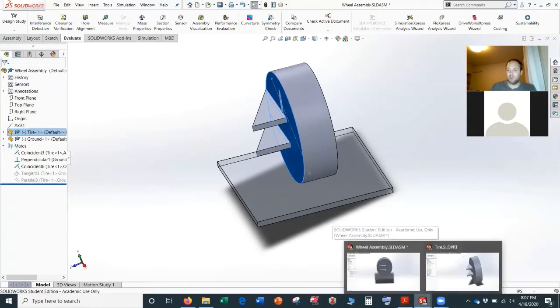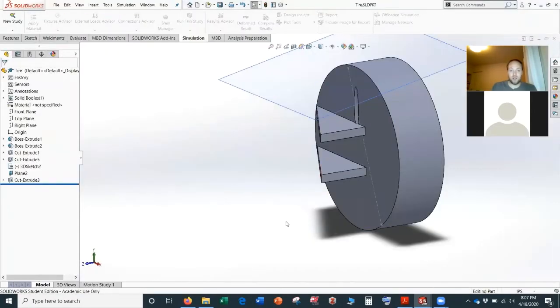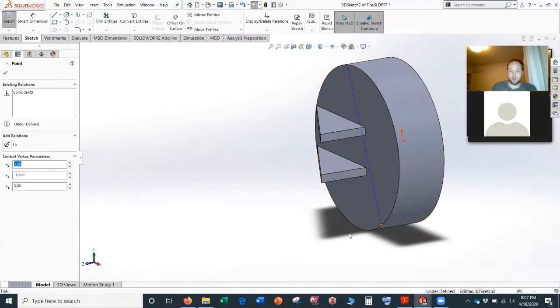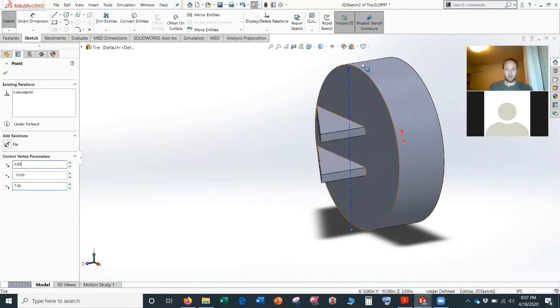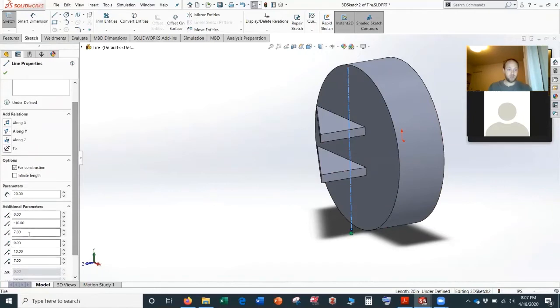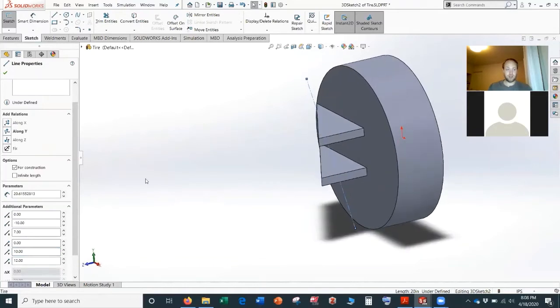You see it's just very subtle though when we have no scrub radius. So let's also add a little bit of scrub radius. I'm going to go to the tire and move this point on the ground. So let's add 3 inches, or maybe even 4. So we'll move out the Z to 7 inches here. And then the top point, we'll move out, and we'll keep a little bit of kingpin inclination. We'll move the top point out maybe to 12. So we'll set our kingpin axis like this.